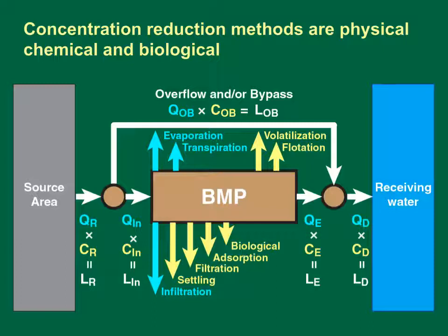It is commonly assumed that bypass flows and overflows are not treated. Outflow concentrations can be greater than inflow concentrations if previously stored constituents are scoured from the BMP, if there is carryover, or if the chemical or biological reactions convert or generate a water quality constituent.